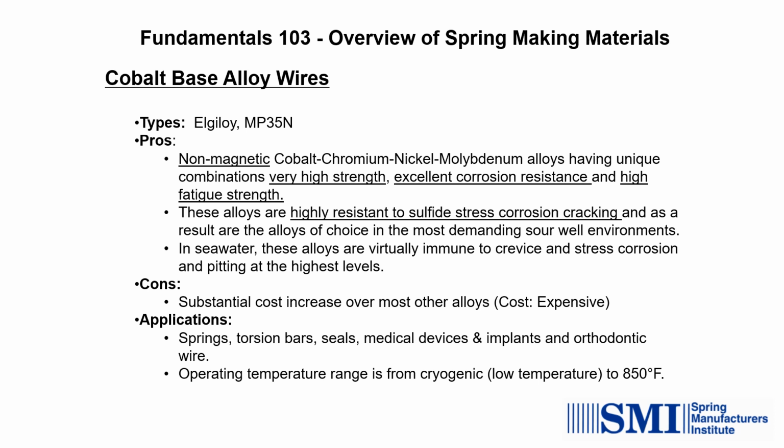Cons: there's a substantial cost increase over most other alloys. The applications: springs, torsion bars, seals, medical devices and implants, and orthodontic wires. Operating temperatures range from cryogenic to 850 degrees Fahrenheit.